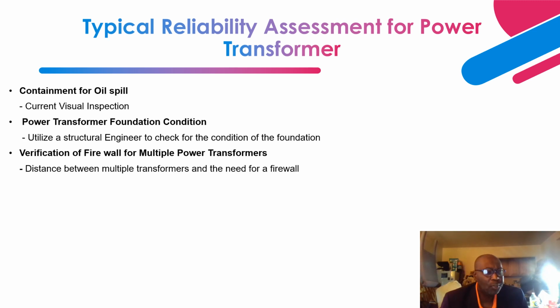So next, we'll move to containment for oil spill. As you know, a power transformer sits on a concrete foundation, and to perform this inspection, you need a structural engineer, a specialist that can help you do the assessment. The goal is to inspect that foundation and the containment. Around the containment, you have gravel that is supposed to contain the oil if there should be a spill. Like I indicated, it's a structural engineer that helps you do this assessment.